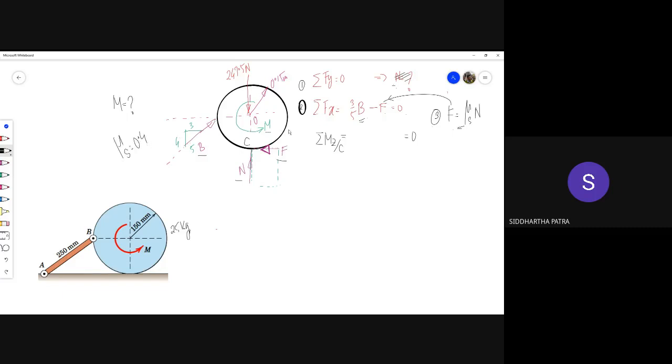Achha, can you tell me, is there a way to get the value of the normal force without getting the value of B? I think there is a way. Of course, you need to incorporate this equation. What you can do is you can resolve the forces in x prime and y prime coordinate system. And by taking the y prime components of all the forces, that would prevent any term of B in your equation.